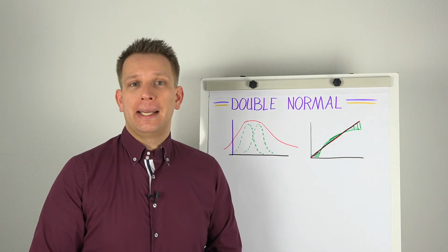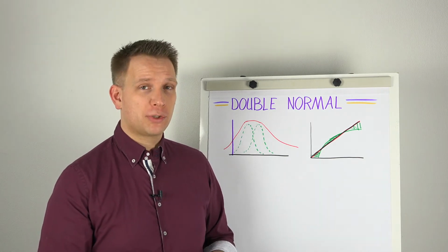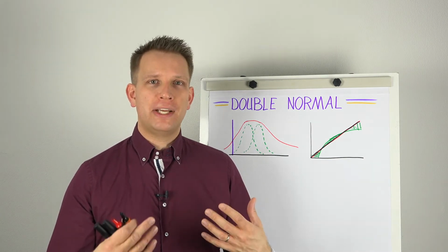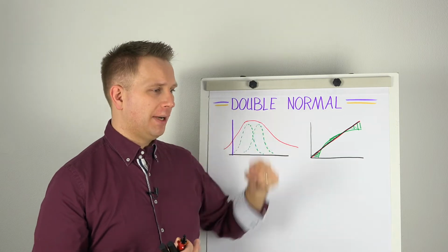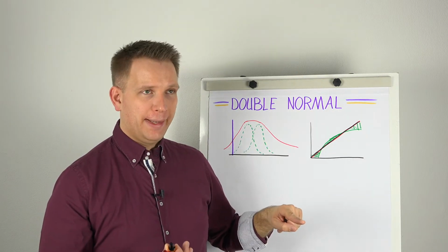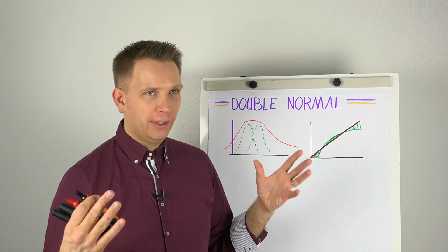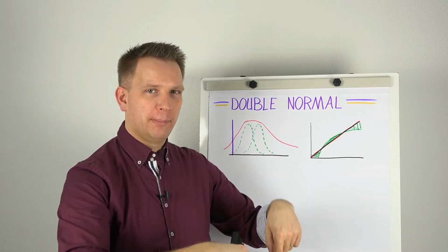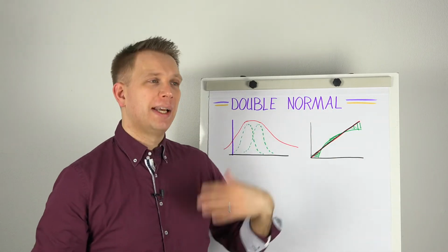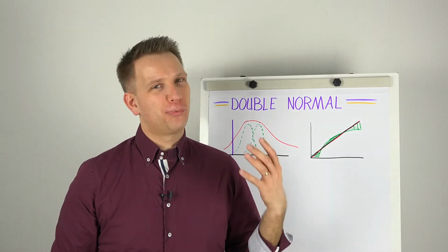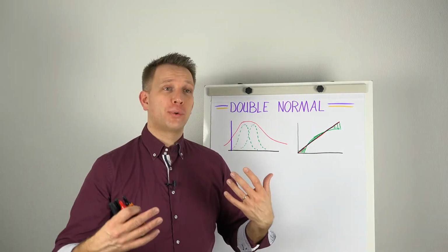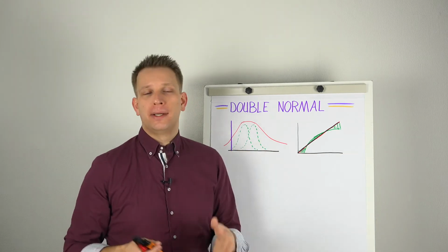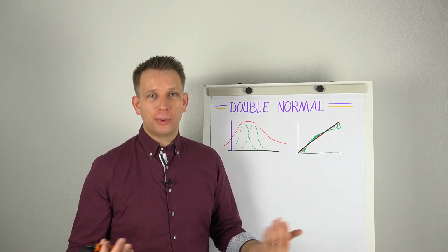What you see in an SPC chart, a statistical process control chart, or a run chart, is that we can check for this rule of stratification. And stratification is that it goes up and down and up and down and up and down. And then the standard rules have either 14 or 15 consecutive points above the average, below the average, above the average, below the average. And then it gives you an alarm that says, well, you're probably looking at 2 data sets. And of course, one of the better ways is to actually go to the process. And if you know that this is happening, just manually sort them out to at least prove your theory.